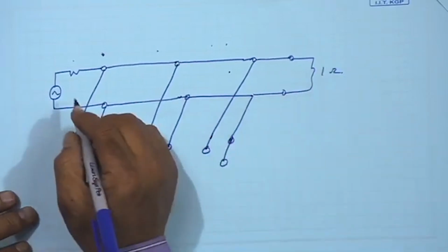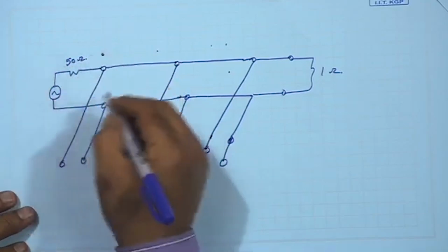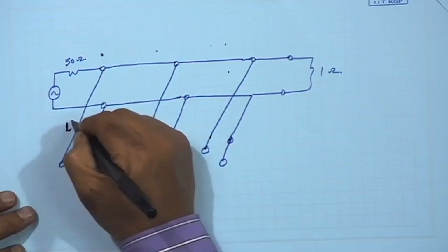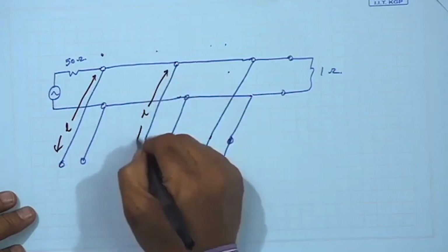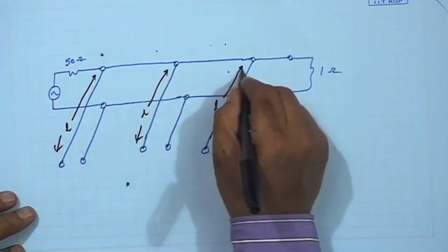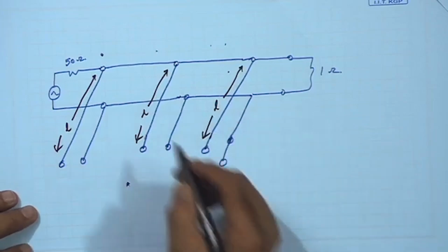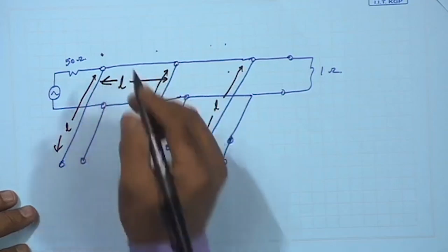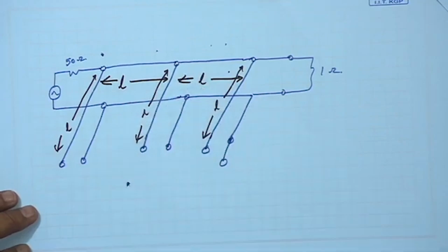So, you see this is 50 ohm, and these are all, now I will say L lengths, all are L lengths. L is lambda by 8. So, there are 3 such, and this is also a unit length L, this is also unit length L. So, all lengths are L, only they differ by their characteristic impedance.